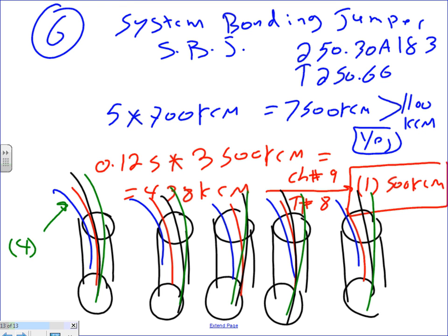This is your 4 conductors of 700 kcmil, and I'm going to say THHN. I can go find you a conduit based on that one. THHN, 700 kcmil. We're inside the building, so let's use EMT. Anybody can get me the answer for that one? EMT 700 kcmil. Well, I don't know if EMT can fit that. It goes all the way up to 500. We might have to go to rigid to get 600. As long as I'm not pulling these conductors, I can make them as high as I could.